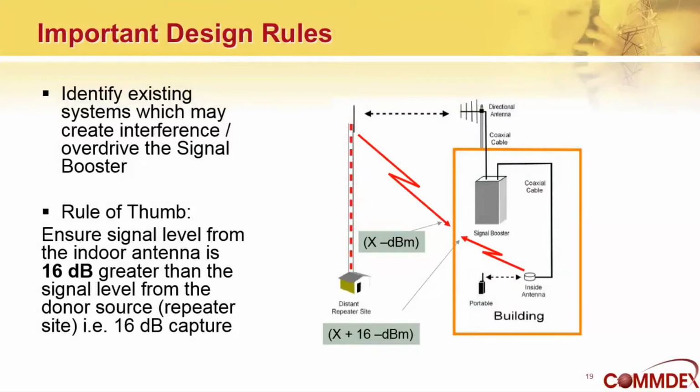So when we're designing these distributed antenna systems, we have to find what buildings we want to put them in and which don't require them. We can't afford to put them in every building in town, but we have to prioritize which buildings really need them. So we have to identify which ones may be a problem. Well, the rule of thumb that's come along in the industry over the years is that if we have about 16 dB loss going through the walls of the building or greater, it's potentially a candidate for a distributed antenna system.